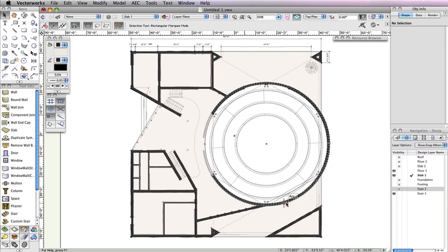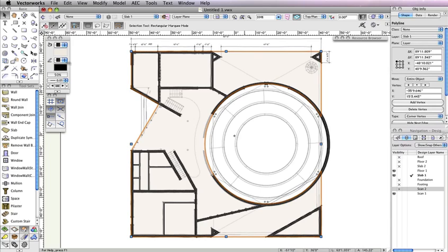We're almost done creating the slab. Now we need to clip a few more extraneous areas before we can complete the polygon that will be used for the slab. This time, we'll use the Clip tool as a different approach to clipping objects. To begin, select the polygon. Then select the Clip tool from the basic tool palette. Also in the toolbar, enable the first mode, Exclusion mode, and the fifth mode, Polygon mode.